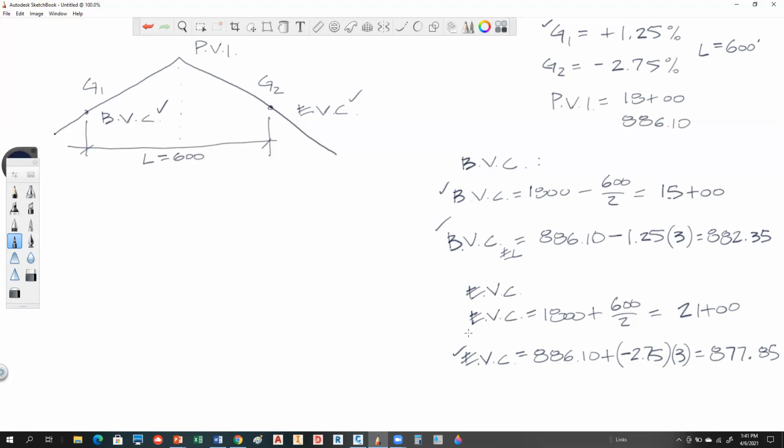Because if slope is defined as rise over run, and you divide rise by run in feet, your slope is going to be feet per foot, which is unitless, right? But we are not expressed in feet per foot. We're expressed in percent grade, so that's feet per 100 feet. So it's a unit thing.